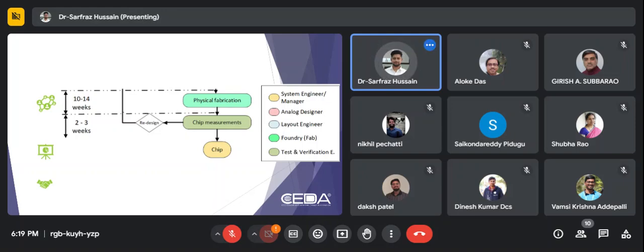And if there is any mistake or any problem with the IC, then we again need to redesign it. So basically, we don't prefer redesigning it. That is why it's very important that before generating the GDS2 file, we confirm that our design is all correct and that whatever parameters we are putting in, we are getting a good result. So before that, we need to verify.